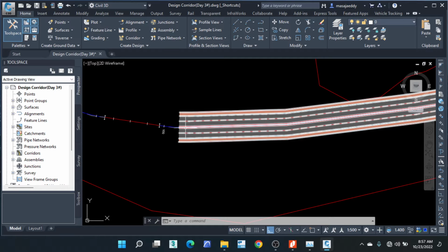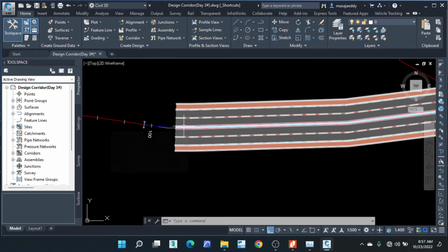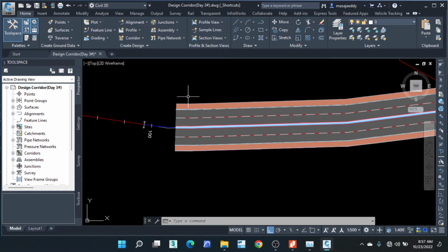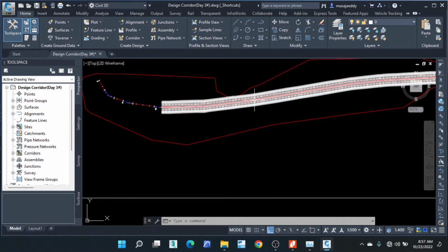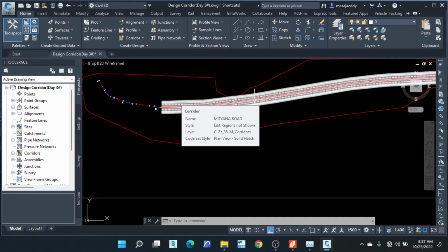We are suggesting that we are going to be modeling an intersection, but we are going to be remodeling the corridor from scratch. So I'm suggesting that perhaps we remove this one, then we find a point where we're supposed to have a junction by importing in the images. We identify where we had an intersection along the road, then we revoke the corridor straight from that point, because now we have a corridor that is not going to be very functional while we are developing the intersection. So it's better if you model it from scratch.